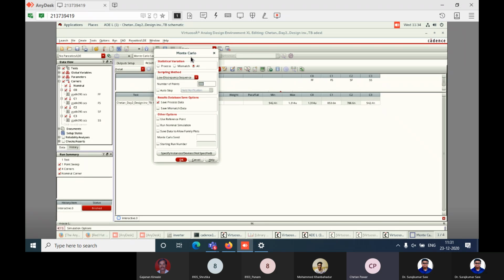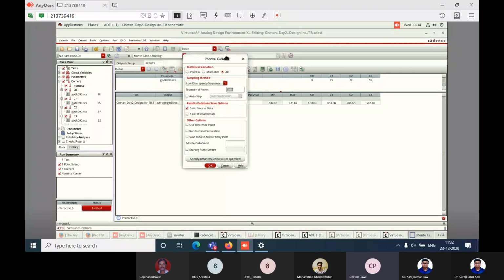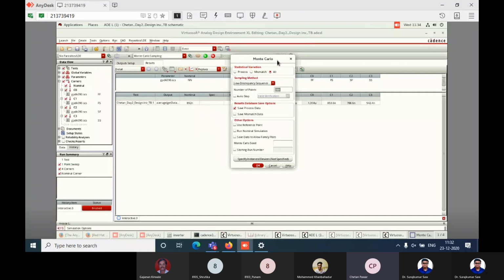Poonam, you select that Monte Carlo analysis. So the top window is there, na? Beside the run, all those things here. That single run switch and corner window is there, right? Single run switch. In that drop down, you click Monte Carlo, on the left hand side. Yes, there. Monte Carlo. Right. Okay, fine. Yeah, Monte Carlo sampling.